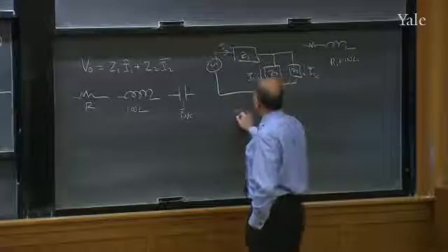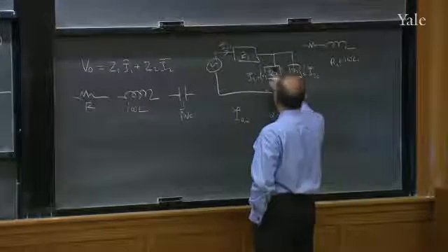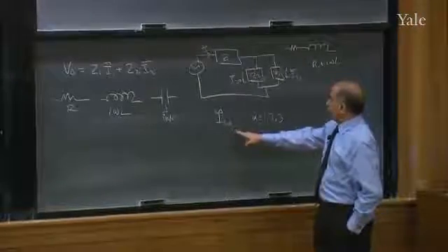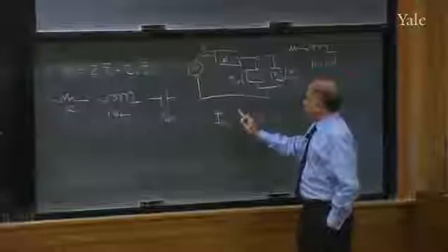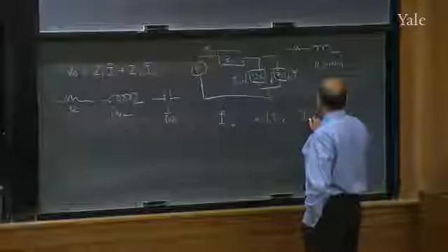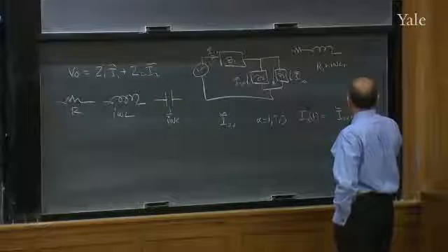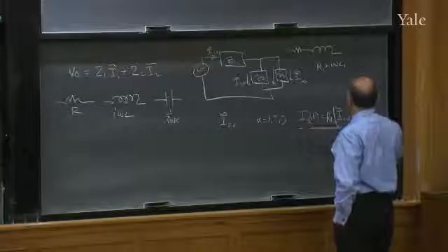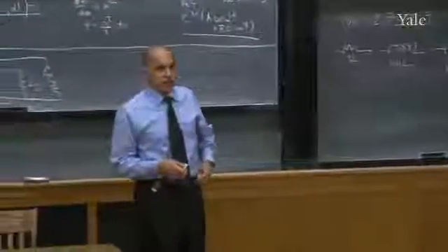At the end, you would have found every current I twiddle α, where α is 1, 2, or 3 in this problem, right? You will solve these DC-like equations and find these DC-like currents, but they will be complex. What is the relation of this to the actual current flowing through the actual circuit element? The answer is I_α(t) will be I twiddle α times e^{iωt}, then take the real part. That's the algorithm. That's the relation between these time-independent functions.